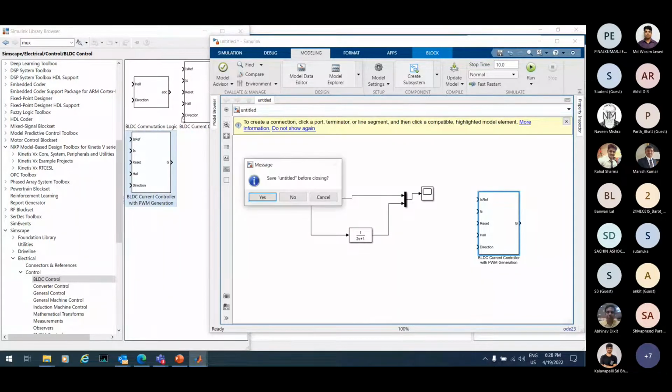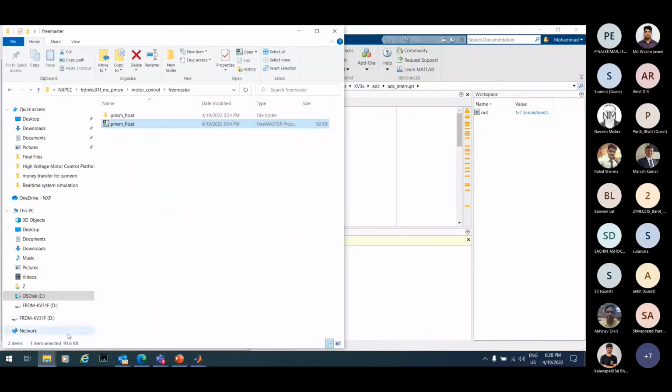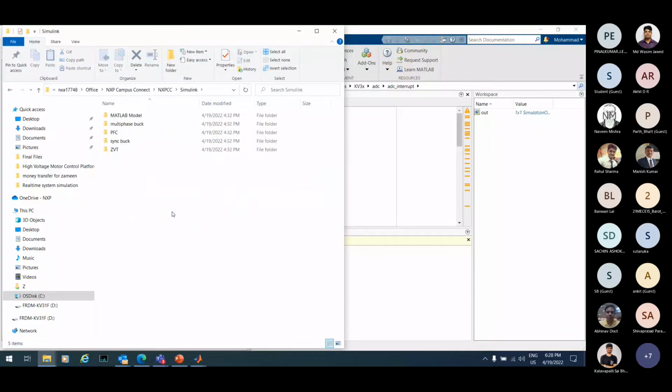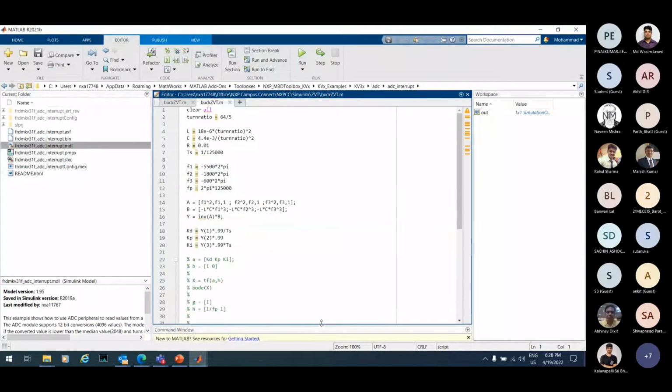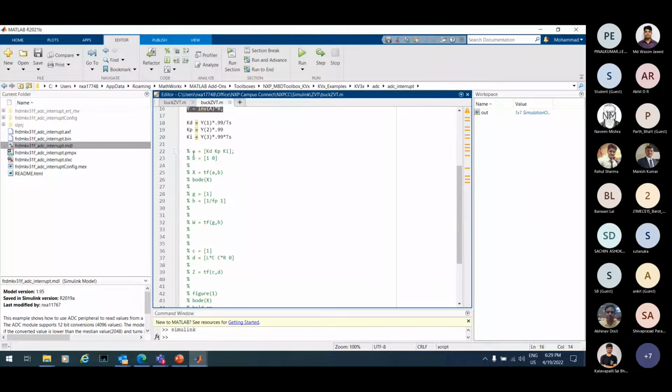So this is one way, and the other way, as I said there are two ways that you can do the simulations, is what I generally do: write my equations based on my circuit. I have a circuit. In my circuit, there will be inductors, capacitors, and resistors, and for every switching point, how those things are related to each other. Then I can have those, and this will give me my control loops.